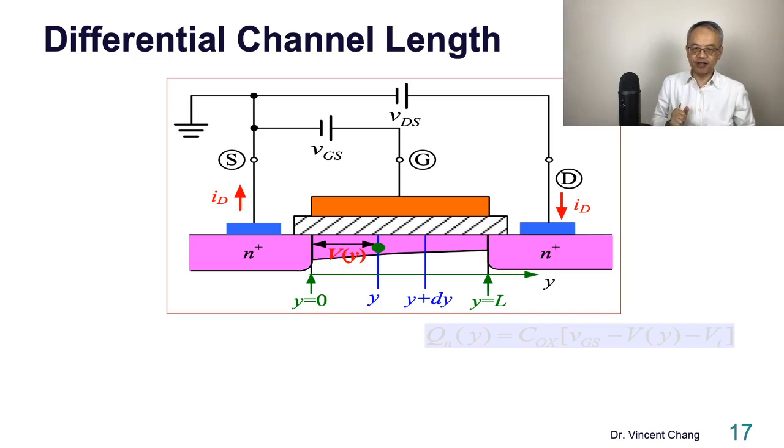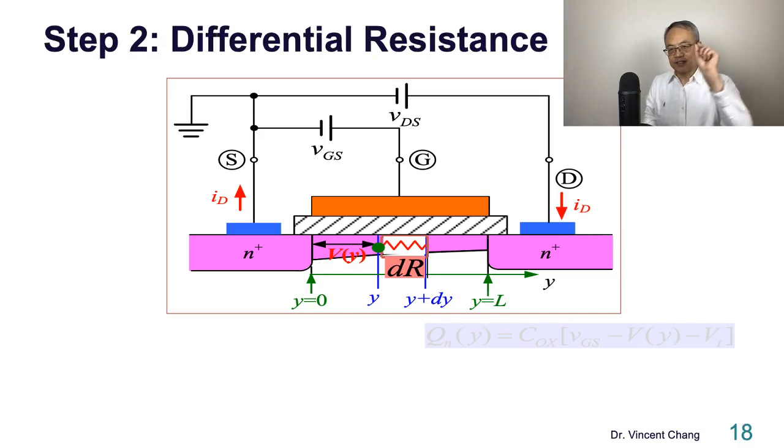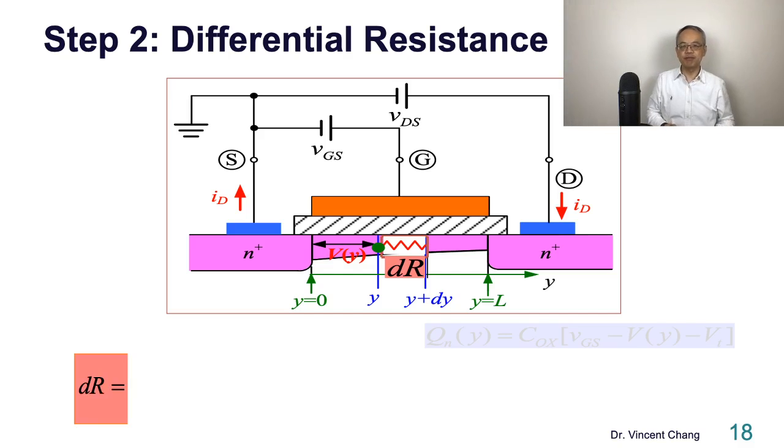Differential channel length. Let's move on from y to y plus a differential length dy, because it's the concept of a differential, right? Within a very small distance, the channel behaves like a resistance. The differential resistance dR between y and y plus dy.